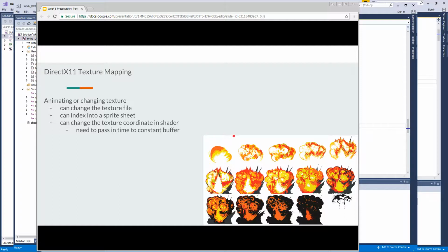In this case, the U texture coordinate at the end of this first cell, counting 1, 2, 3, 4, 5, would be 1.0 divided by 5, so the U would be 0.2 right here. And the V here would be 0.33 because it's a third. There's 3 rows going down. So that's another way of creating animated textures on an object.